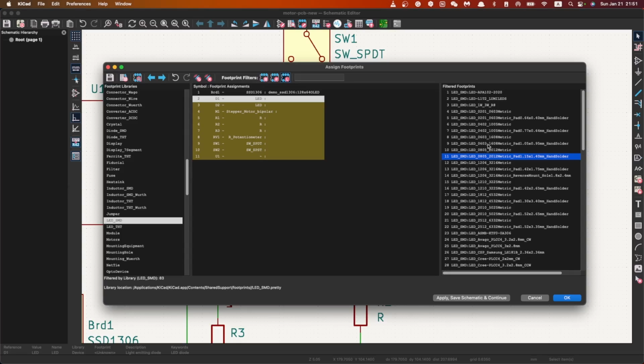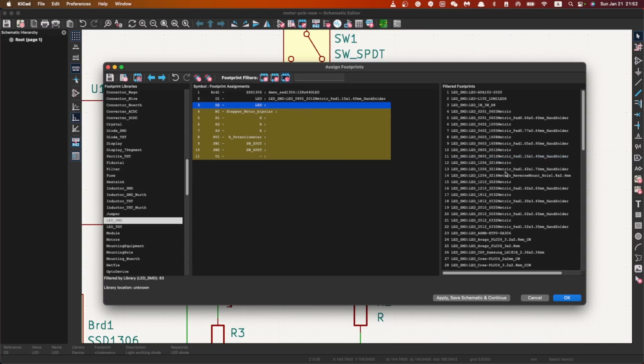And for 0603, it could be challenging, but might be doable. But for 0805, it's definitely doable with your hand solder skills. So I recommend everyone here, if you want to solder anything SMD on your PCB board, use 0805. Okay, so let's use 0805 for them both.